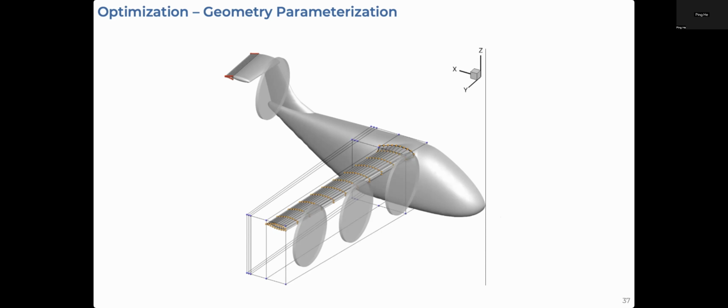So in this top part of the graph, the normalized lift tracks the elliptical distribution quite well, with some oscillations where the propellers are, where we have upgoing and downgoing swirl from the propeller regions. The twist distribution along the wingspan is generally constant, with minor oscillations near the root that is trying to handle some separation between the fuselage and the wing, and an oscillation at the tip that helps decrease induced drag.